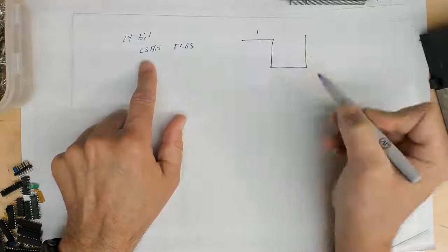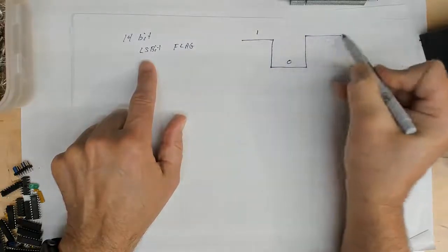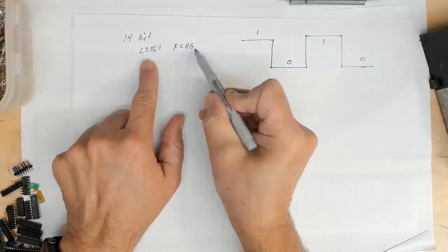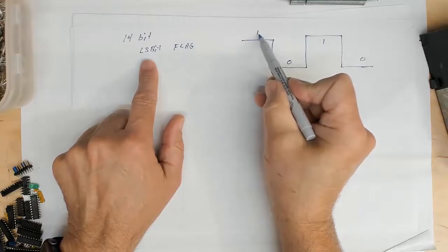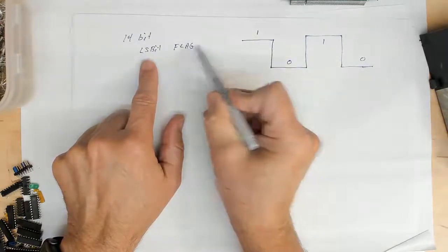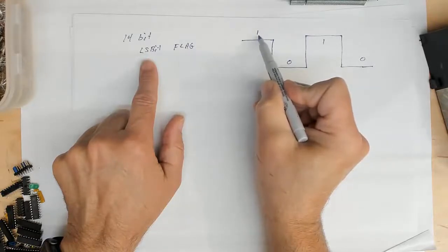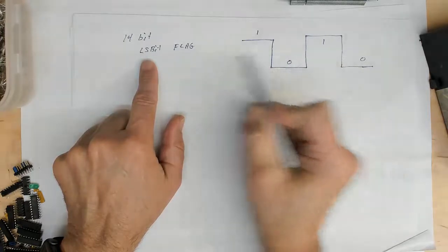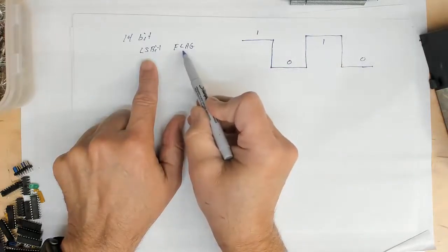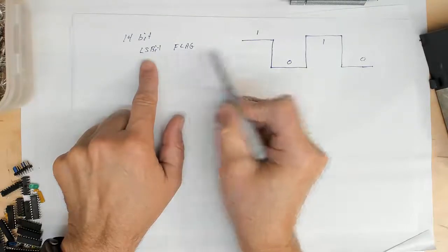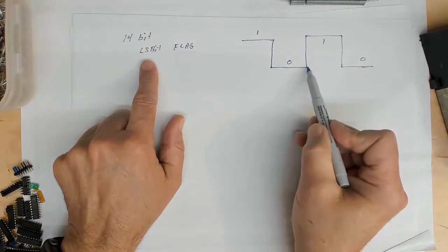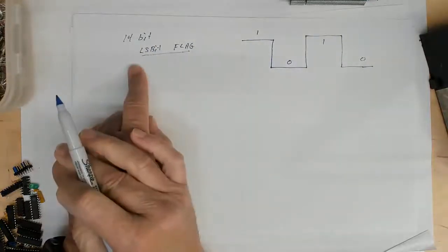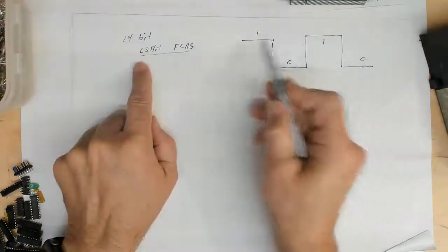So here that flag is going to be equal to 1. Here that flag is equal to 0. Here the flag's 1. Flag 0 again. And so we can see that this flag of the least significant bit is actually the same value as the output pin. So if that flag is 1, our output pin is 1 for the timer output. And if that flag is 0, then our output pin goes to 0. So that flag we can see already, they could just be sending that bit, that least significant bit, out as the pin for the timer out. Okay, so that's one thing that we know from the spec sheet: they're using that least significant bit as the flag. And also that least significant bit represents the output pin.